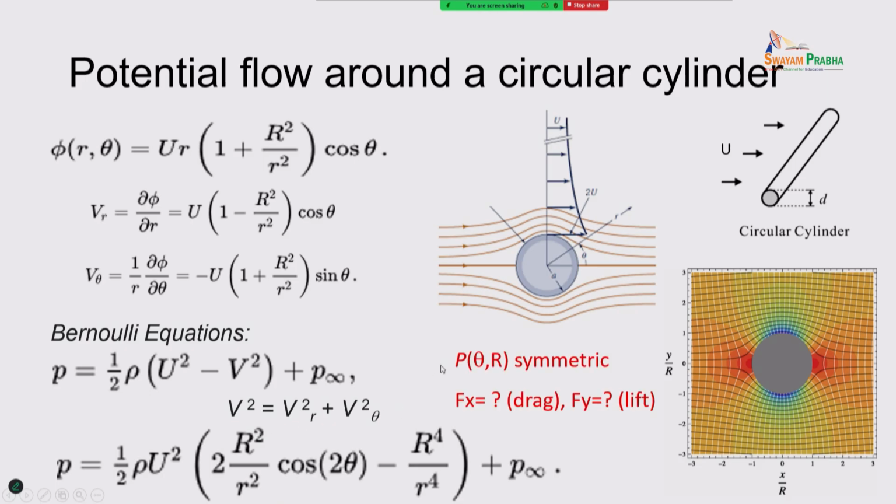So what do you think the force is, in the x direction and in the y direction? What's Fx? You can do the integration, but look at the symmetry. What do you first think? It's 0, right? And Fy, perpendicular to the fluid direction, usually we call the lift, that is 0 too, it's symmetric.